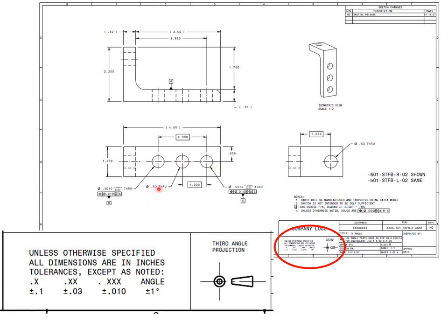So this dimension now has been increased, or the diameter has been increased. And then at the end you have the date of the change and typically the initials. Then it gets processed and released again through document control. It's a big deal when you have to do this again, but it's part of the contract and you need to properly go through the process of releasing it.